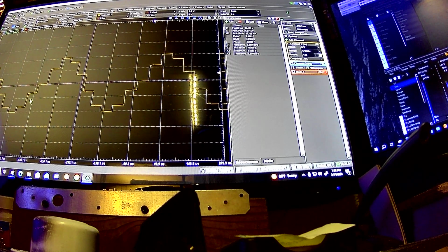It's really a low pass filter, and it just depends on how sharp your transition needs to be and what order you need to use, and that would require some experimentation. But I'd think a first or second order filter would go a long way in helping, depending on what you set your corner frequency to be. The good thing is, I think it could be a fixed corner frequency in all likelihood.